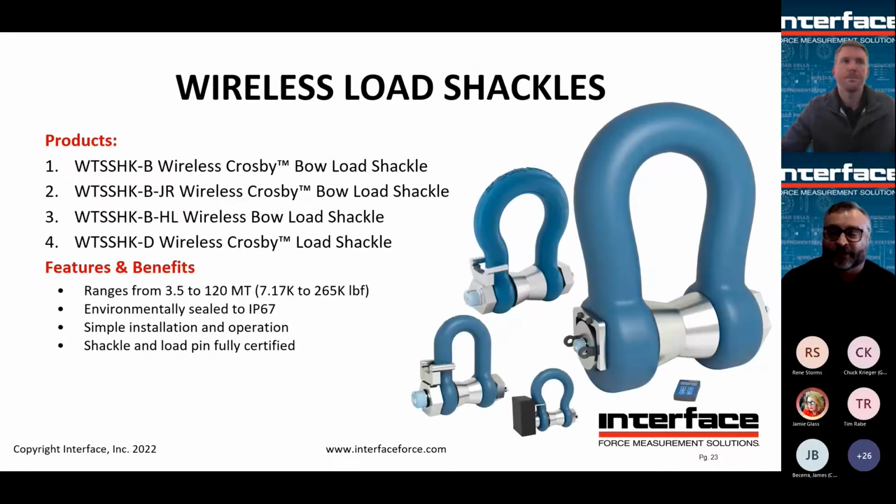So here are some more examples of these load shackles. This is somewhat to scale. You can see the little handheld display down there, and you see the little blue wireless module mounted on the end. That big shackle to the right is actually a 2 million pound load shackle, if you can imagine that. You can imagine lifting or hoisting something valuable. It's important to monitor while you're doing that to make sure it's not hung up, or if the load changes during the lift, there's something going on, needs to be addressed, you can stop and review. Next slide, please.